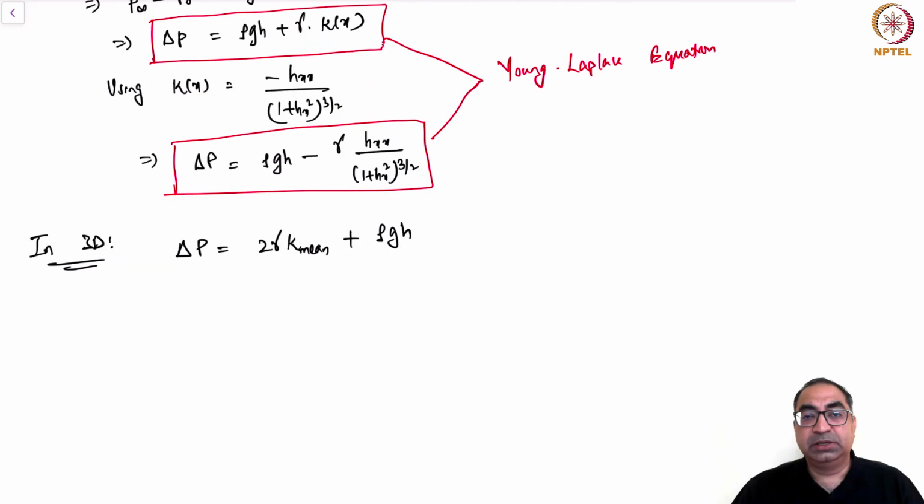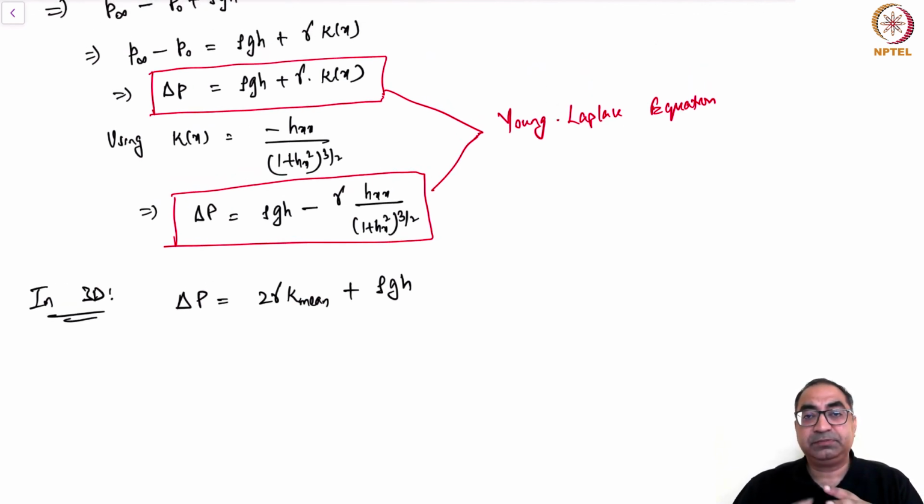Okay. So what we have done in this lecture is we have considered the case of a droplet sitting on a surface, and we have considered the variation of the height. If there are small variations in the height, this will lead to variations in the energy functional. And this variation in the energy functional, we minimized it. We set the variation to 0, and in the process, we got boundary terms at the two contact lines at A and B, and we also got the Euler Lagrange equation.